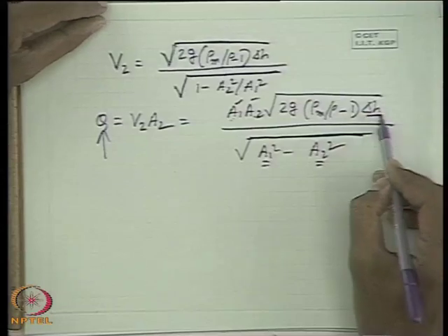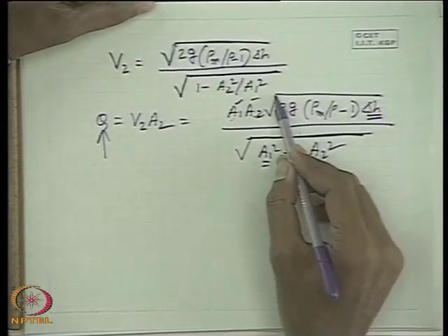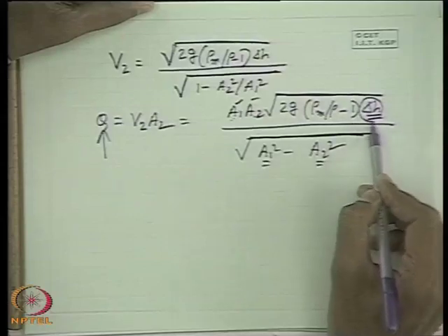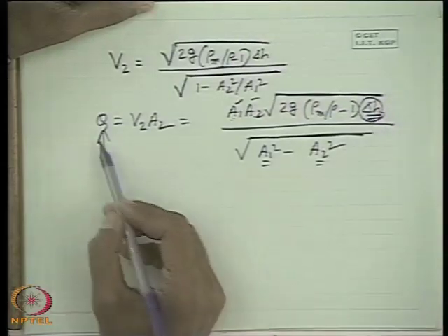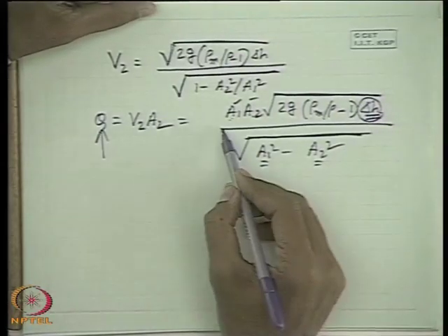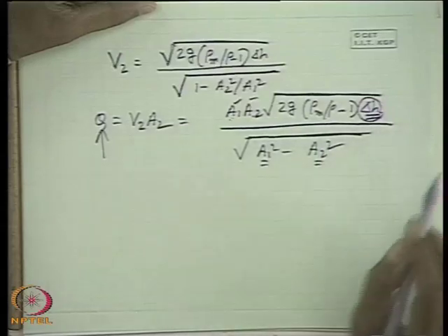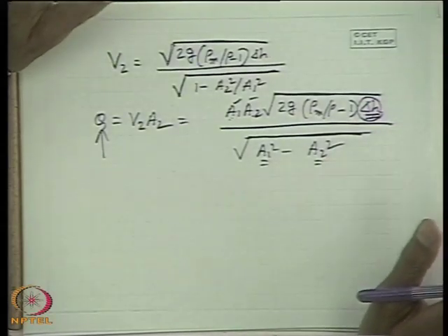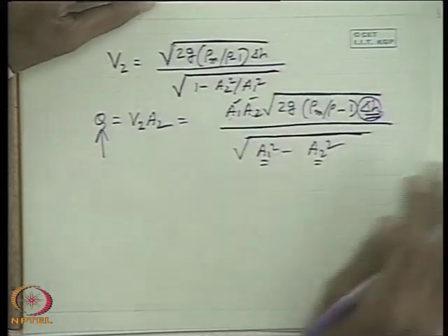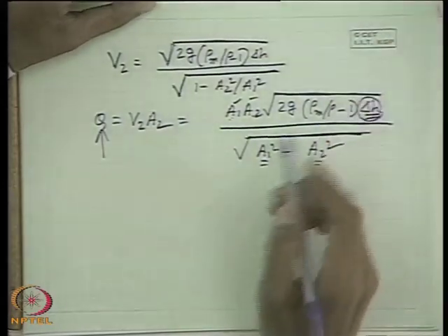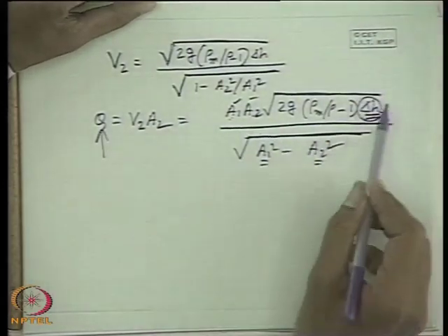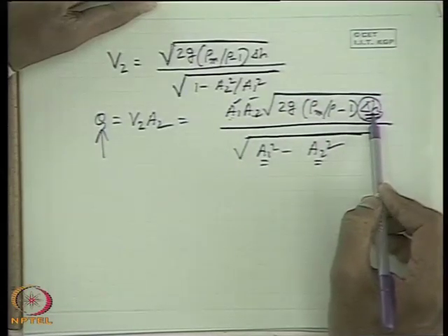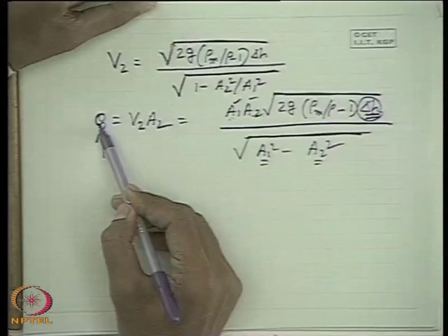And if I know the deflection of the manometer, that means if a manometer is connected between 2 points, the measured value is delta H, which is put into this equation to find out the flow rate. But this equation will always overestimate the actual flow rate. If one measures the actual flow rate, for example, by collecting the fluid, then you will find that by utilizing this equation with the measured values of delta H from the manometer deflection, we will always overestimate this flow rate.